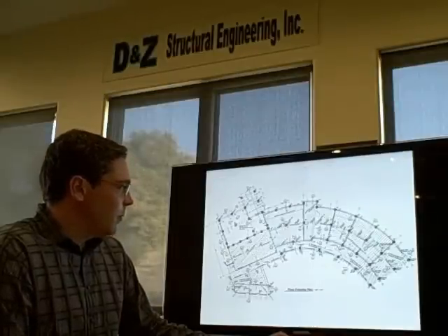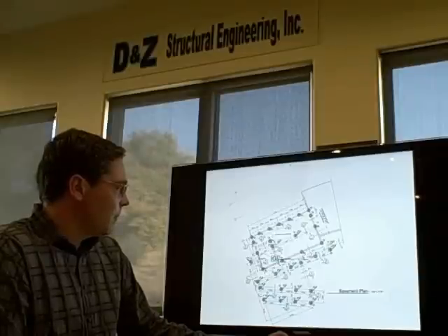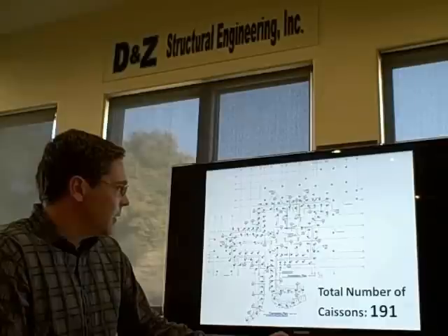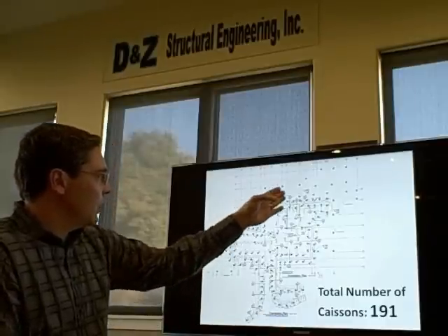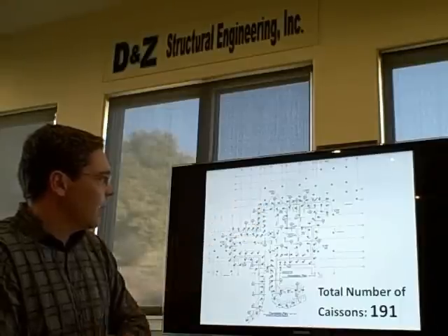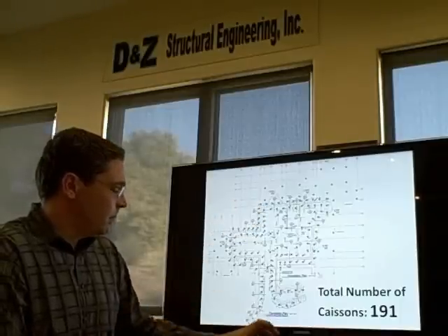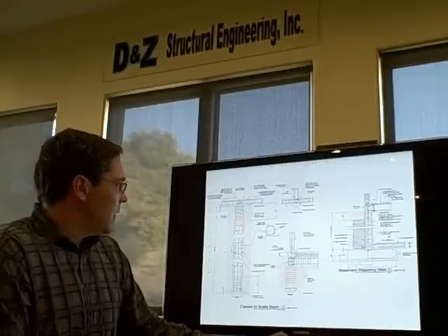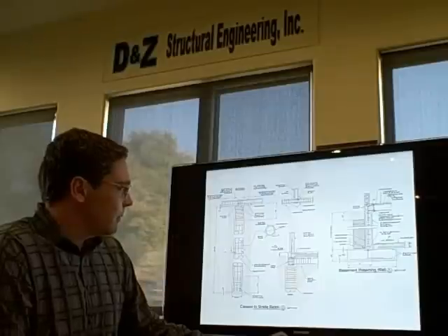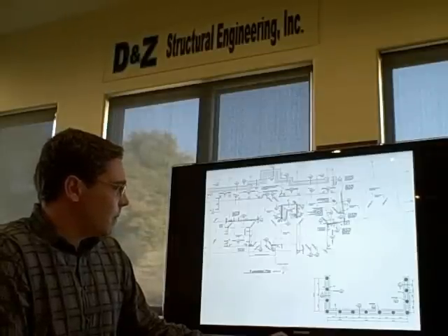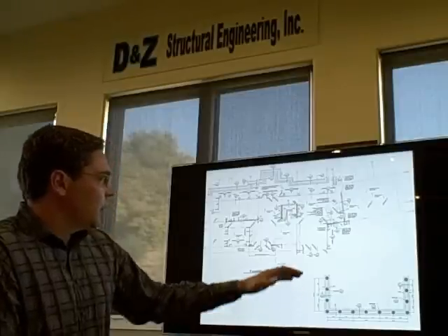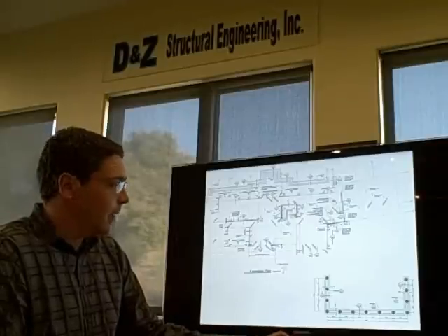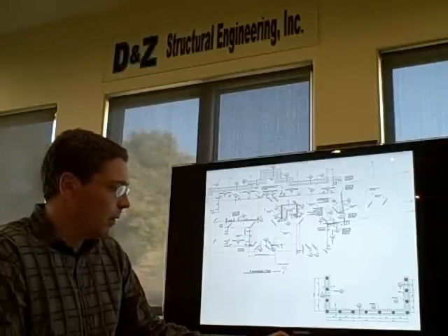We've used them for all types of projects. This is a curved house. This is a very large house with multiple caissons, large retaining walls all the way around, caissons in front and back of the retaining wall foundation. Design utilizing more caissons. Again, a structure where the house was in competent soil, and then out near the parking area we're on a fill area that needed to have better support for the foundation.